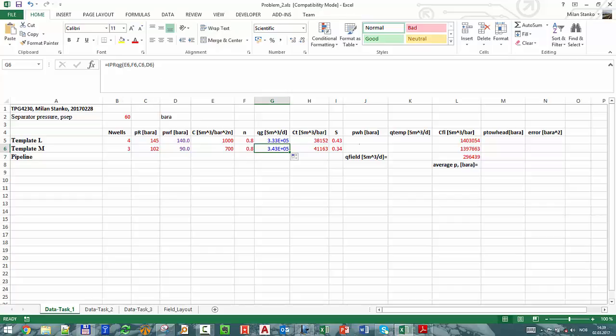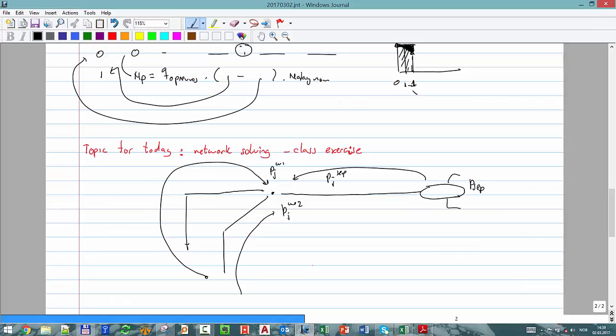Okay, now I'm going to move to the wellhead. I still have to use the rate of one well. Okay, and which equation should I use here to get the wellhead pressure? But tubing we had two, right? So which one? P2. Why? Because we make our system, right? The fluid is going in that direction. Here we have PWF, PWH. Which one is 1? Which one is 2? 1 here, 2 here. So we need P2 if we have P1.